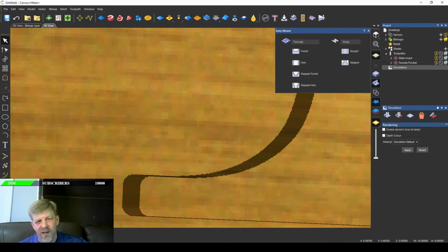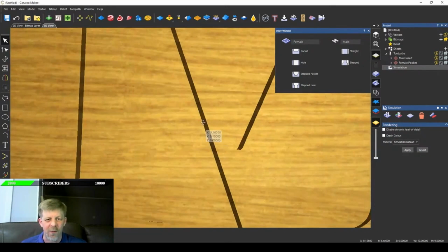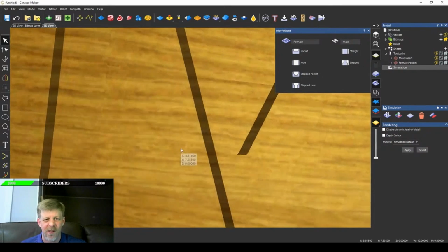What you can do is, instead of cutting all the way through where I did that profile pass, sometimes what you can do is what I call onion skinning. It's where you leave just a little bit at the bottom instead of setting that 1 inch depth of cut, just a few thousandths off of that full depth of cut, and it'll leave really thin material at the bottom, and that way you don't have to add bridges. That's a way around bridges, but you still would have to cut through that piece of material that's going to be left at the bottom.